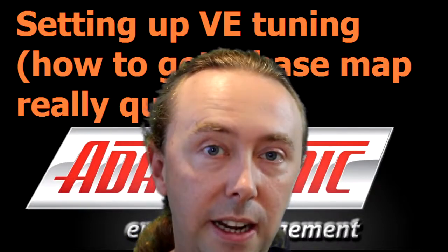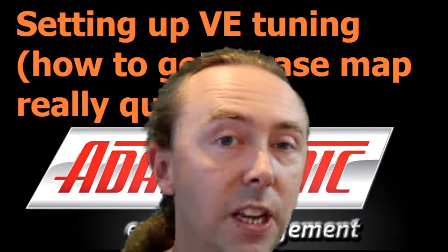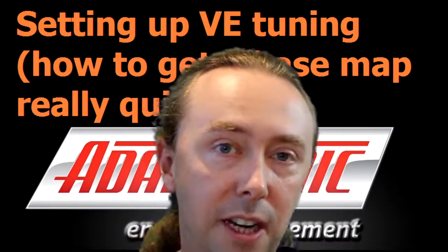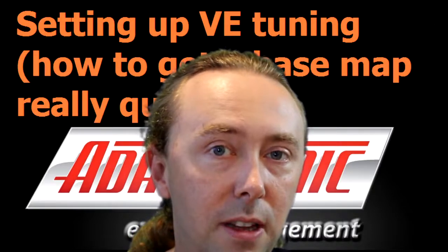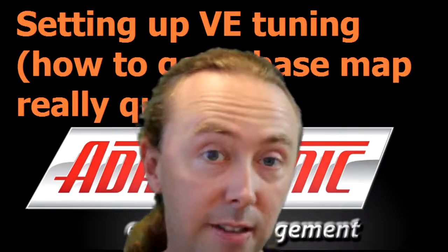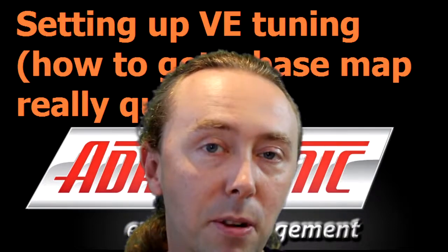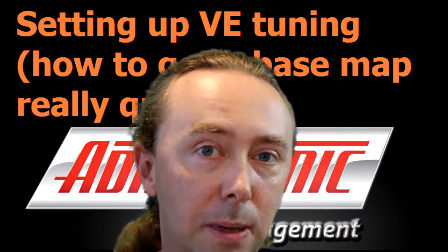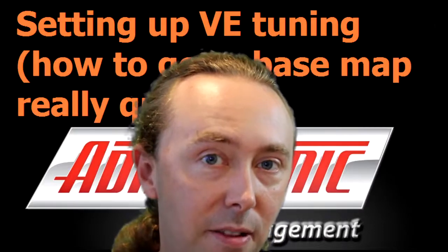scratch. Here's the theory. Every time an engine goes through its complete cycle, which is 720 degrees for a 4-stroke engine and 360 degrees for a 2-stroke engine, it draws through the swept volume multiplied by the volumetric efficiency. For example, a 4-litre engine operating at 80% volumetric efficiency will draw through 3.2 litres of air in the 720 degree cycle. Knowing this, as well as the manifold air pressure or MAP and the air temperature, the ECU can calculate the mass of the air going through the engine.